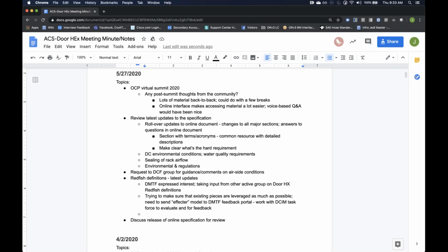You should be able to have a generic effector, and it may end up being the same firmware that's running on a CDU controller will work for quite a number of different units. You should be able to go into a configuration phase and say, this has 1 pump or 3 pumps, or has this specific feature or not, or you have PWM versus a voltage for controlling the speed of a pump.